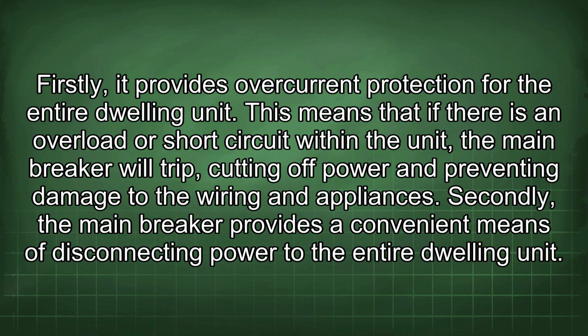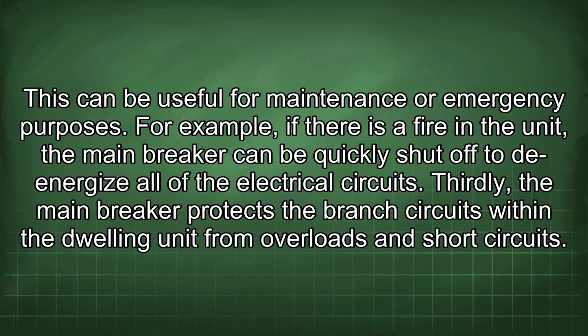Secondly, the main breaker provides a convenient means of disconnecting power to the entire dwelling unit. This can be useful for maintenance or emergency purposes. For example, if there is a fire in the unit, the main breaker can be quickly shut off to de-energize all of the electrical circuits.